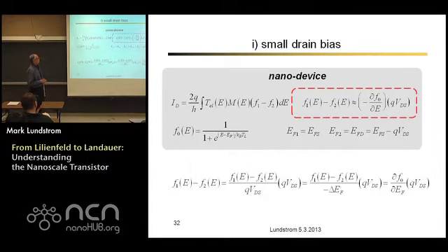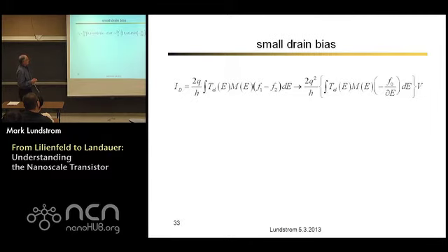Okay. Then just a little more algebra. You can see that the only difference in this formula between the Fermi level and the energy is a minus sign. So I could replace dF0/dEF with minus dF0/dE. Okay. Now I have a classic expression. If we plug that into the current expression, we're going to find that F1 minus F2 is a derivative of a Fermi function times the applied voltage.